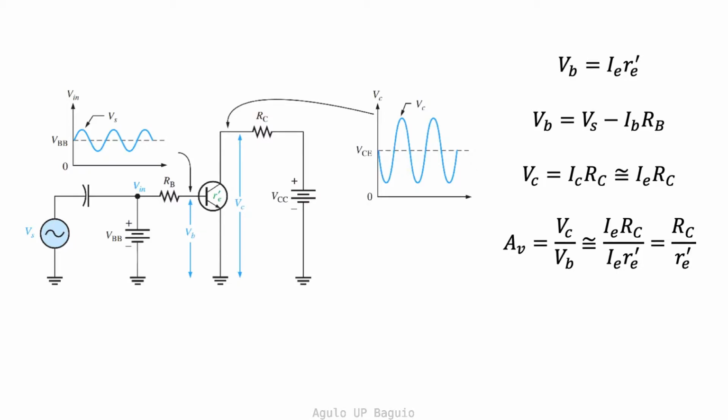The coupling capacitor couples the AC signal to the input of the transistor, but prevents the DC signal from affecting the input AC signal. At the input Vin, the AC signal is shifted upward as seen in the V versus T graph, and the shift corresponds to the DC signal. Keep this in mind. In our discussions, we'll talk only about the AC signal being amplified. The only effect of the DC signal is to shift the AC signal upward or downward in the voltage scale.